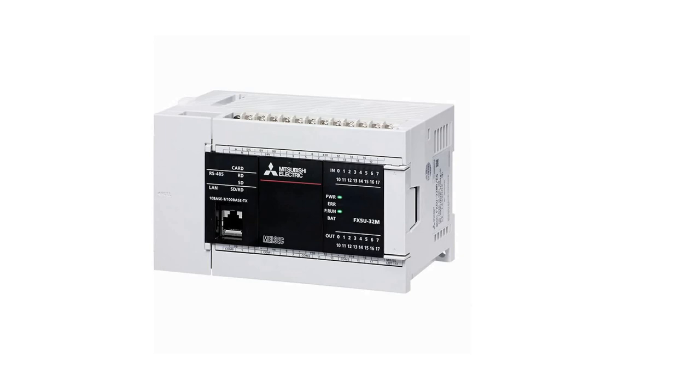The input wire is connected to the PLC and the output wire goes to the system. Considering the example of that hydraulic system again, the input to the PLC is a sensor and the output from the PLC is an actuator. Actuator is nothing but our solenoid valve. As the solenoid valve operates, the system operates, that is the hydraulic cylinder operates.